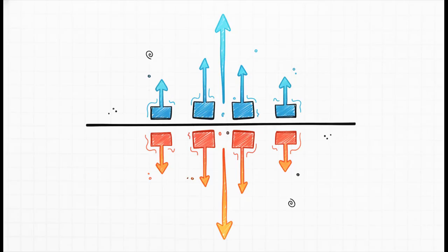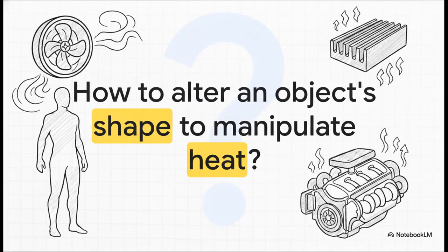And that brings us to the massive takeaway of this entire explainer. We literally had to do all of that complex fluid math because the momentum equations and the energy equations physically mirror each other. Knowing exactly how the fluid physically moves, drags, and churns is the only way to predict exactly how the heat will transfer into it. The velocity gradients strictly dictate the temperature gradients. We started this whole thing by asking why a fan cools you down. Well, it physically sweeps away that heated thermal boundary layer, forcing your body to constantly heat new, cooler air.